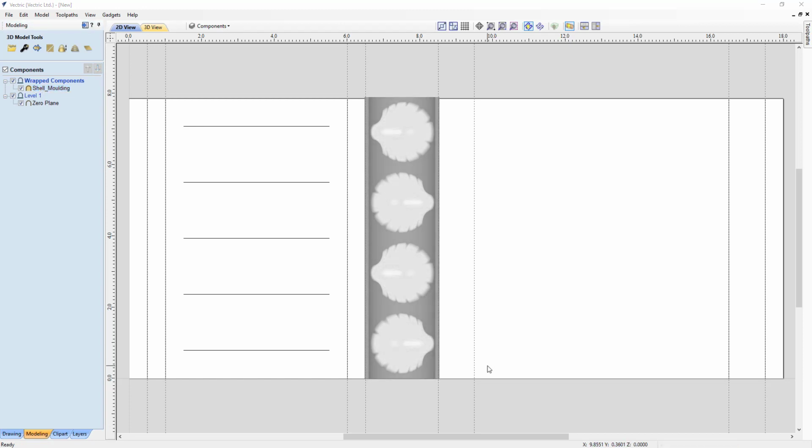So the next section we're going to create is this piece right here between these two guidelines. And we're actually going to spiral some 3D clip art all the way around our column 2 times. So that way we'll have a nice little wrap all the way around. Now, to do that, if you happen to have vCarve Pro or Aspire, then like I'd mentioned before, you have a gadget in your wrapping section called Spiral Layout, and that will create all the vectors you need for that. But we're going to do it by hand right now.